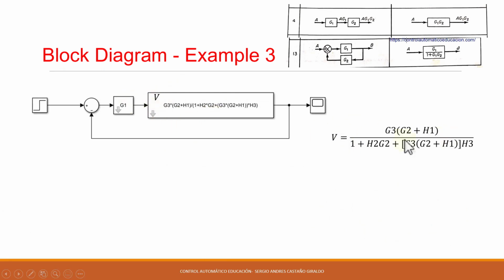So now I have V here, and I can once again use equation number 13, which would be the direct loop. In this case, it's K1 times V, as we have here, with feedback here, since we have negative feedback. So, plus 1 plus the direct loop, which in this case is K1 times V again, K1 times V times the feedback. But for the feedback, I don't have anything. So it's a unity feedback, which means we just multiply by 1, and the 1 is simply omitted.